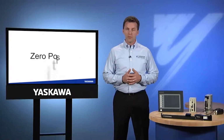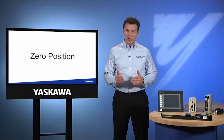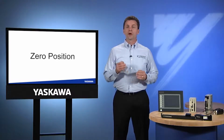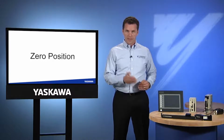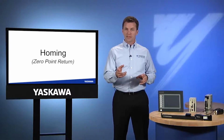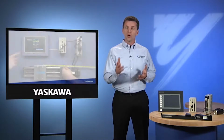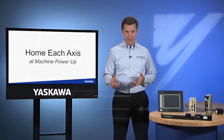Absolute positions and moves only make sense when compared to the absolute position which the controller has identified as 0. The machine requires a repeatable method to find this 0 point. This method is often called homing, or 0-point return. To reorient an axis that may have been moved while the power is off, the controller needs to home each axis every time the machine powers up.